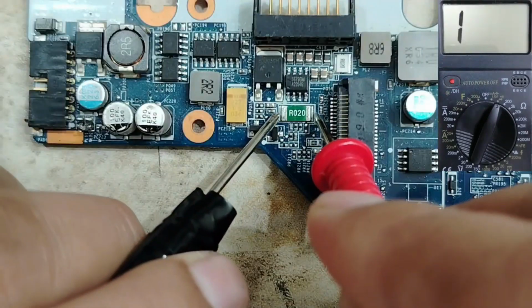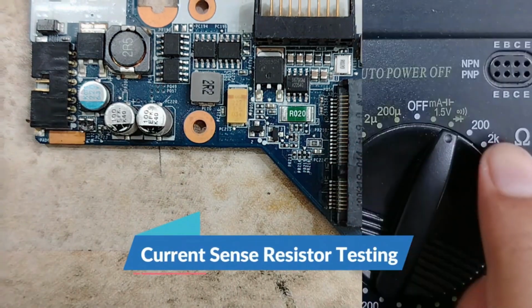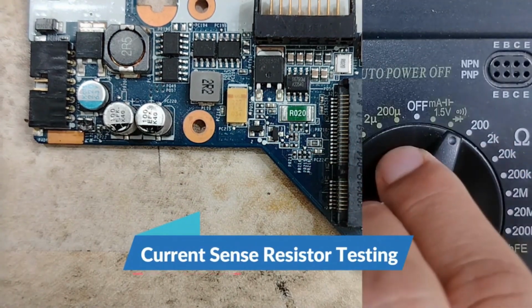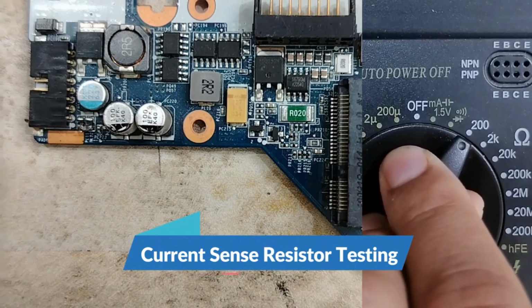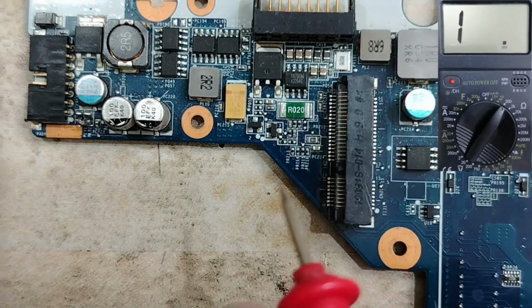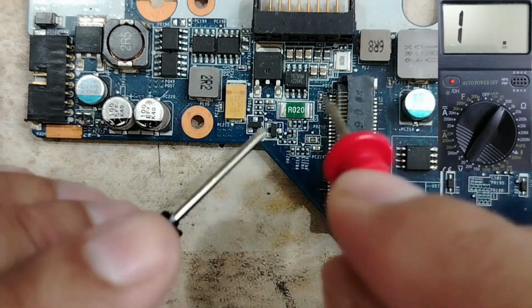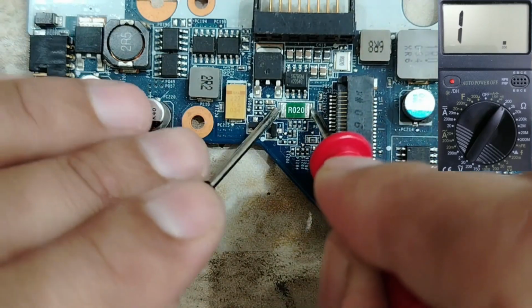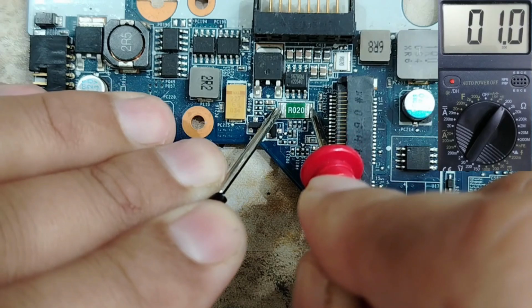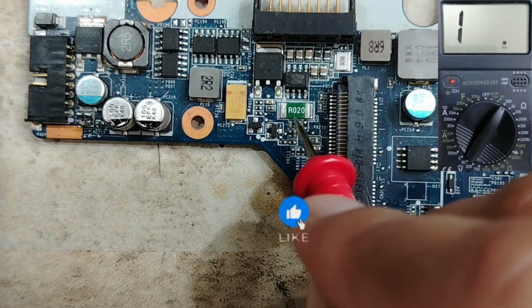If you use the continuity option, you will find about 0 in the multimeter, or you can test it using the resistance option. So if I check this resistor, I can find about 1 ohm. It could be less or a little bit higher, 1.2 ohm, 1 ohm or 0.9 ohm. Do you see? About 1 ohm. So this is a good current sense resistor.